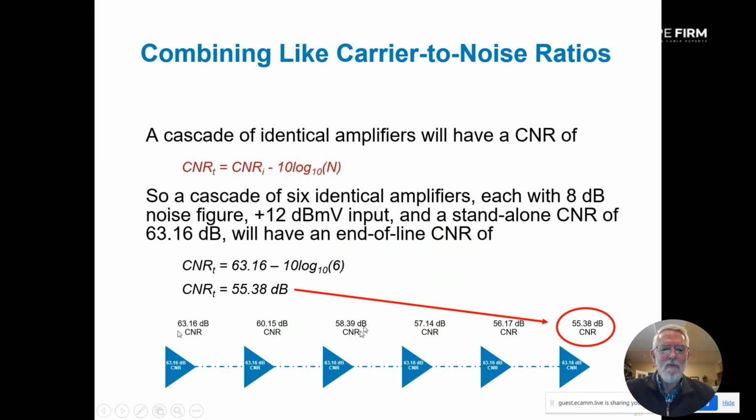And that's almost back to what we talked about when we first introduced the decibel. It's that doubling factor. So you double it and it gets worse by 3 dB. And if you cut it in half, it gets better by 3. And here we can cheat and see if we go to the third amplifier, guess what? It's 3 dB better than our end of line at 6.